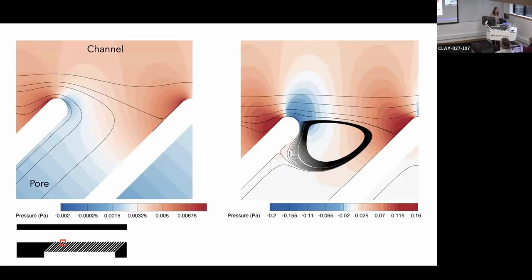Well, you can kind of see a hint of that in the pressure contours. Here you can see my pressure contours are kind of aligned like this. So the pressure gradient is pushing stuff that way, so my pressure gradient is going to do something like this. Over here, if I look, my pressure contours are kind of going this way. So I'm going to get something that pushes my flow in that direction. So I have something that looks like this.